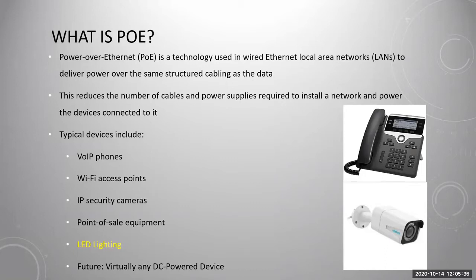And then as PoE grew and progressed over the last 20 plus years, you've gotten more power available and thus higher power devices. And so once 60 watts per port per cable became available, then LED lighting became a realistic application for PoE.